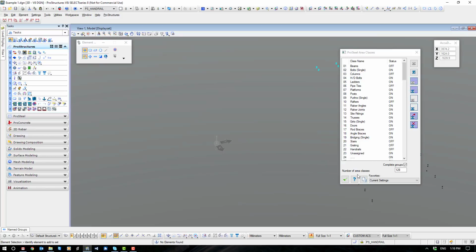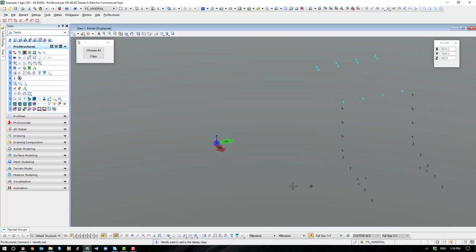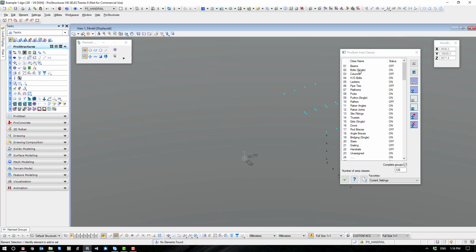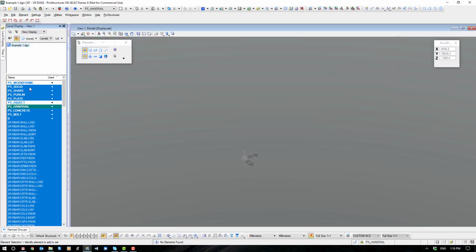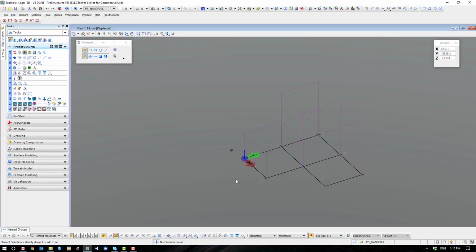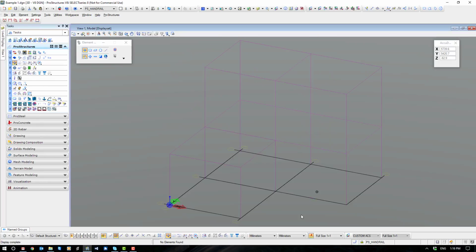And assuming that I'd actually used the right bolts up the top and not structural bolts, any purlin girt bridging bolt we can all bundle into the bolts single, which helps clear off the drawing. Ultimately what will be left is we'll have our work frame, a blank work frame. That is the perfect end result for us.